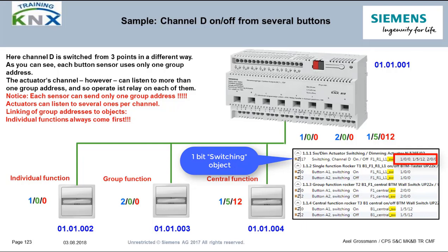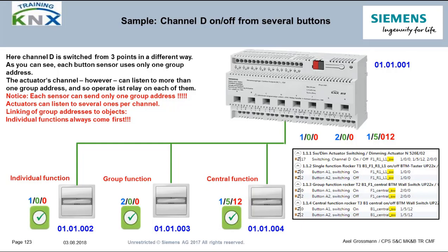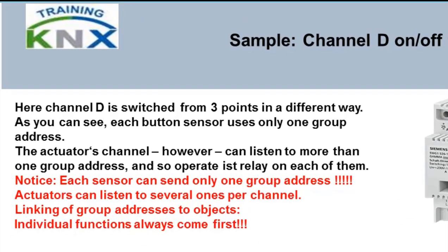Therefore, it wouldn't work if one would assign all single function groups to the object of a push button. So always bear in mind this very essential rule. Every function group requires its own group address. This rule, by the way, is also the only reasonable one.